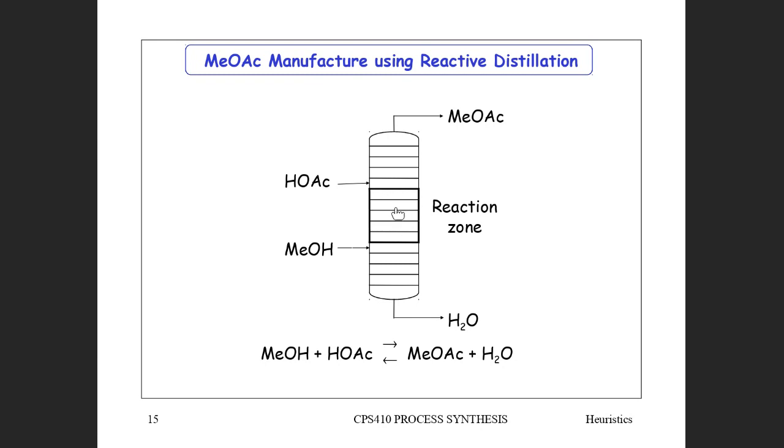So let's say catalytic reactions tend to occur at about 250 degrees. More than that, you get pyrolysis occurring and unwanted side reactions, and less than that, not many catalysts are active at low temperatures. So let's say that most reactions occur at 250 degrees.